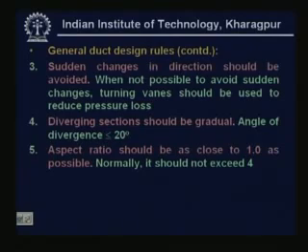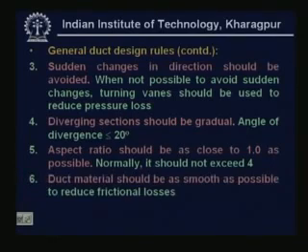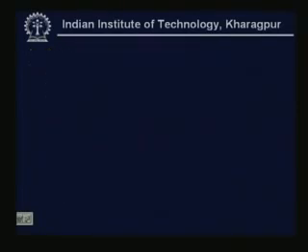And the aspect ratio should be as close to 1 as possible, I have already explained this, and normally it should not exceed 4. And the duct material should be as smooth as possible to reduce frictional losses, okay. So these are the general rules to be followed.